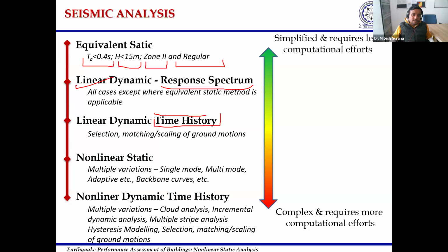For all the cases, linear dynamic response spectrum analysis can be applied, and except where the equivalent static method we are applying, in those cases also the linear dynamic or response spectrum method can be applied. But the cases where the equivalent static method is not applicable, then we need to go for linear dynamic or response spectrum analysis.